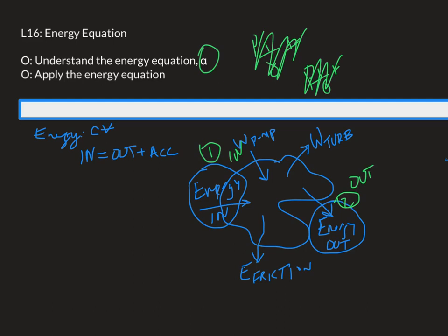You can imagine the friction from that concrete is going to slow down the flow of that water. Okay, and it's going to take some of the mechanical energy and transform it into heat. So that's an important consideration, and we'll see as we go along just how important a consideration that is. I'll mention it on some of the problems here, how big that friction term can get.